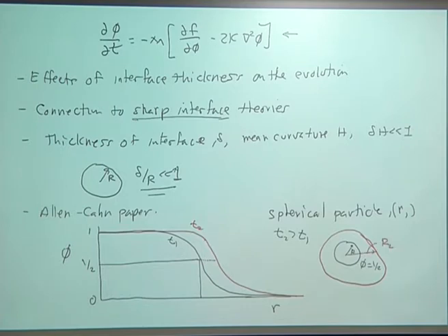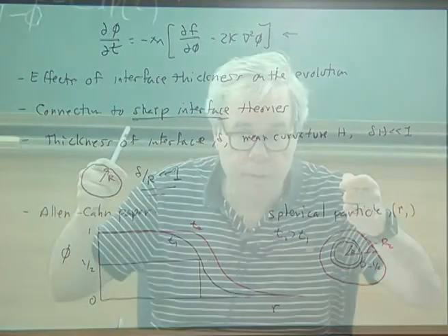To R2. So it gets bigger. For those of you who have not seen phase field models, what you're doing here is you're looking at level curves, or values of the order parameter. You can pick whatever value you want between 0 and 1, and they're level curves, if you look at them in this picture on the right-hand side. These level curves move as a function of time, and you know where the particle interface is by choosing a particular value of that level curve. Let's say phi is equal to 1/2. That's right in the middle of the interface, okay?